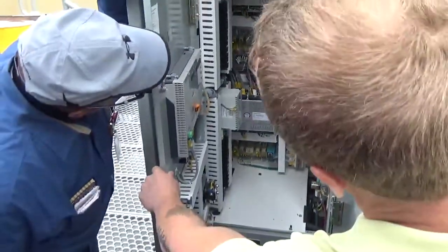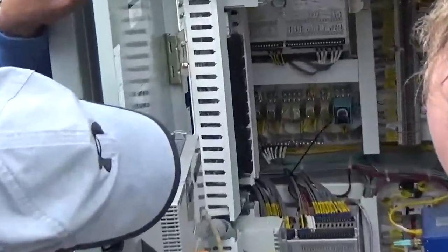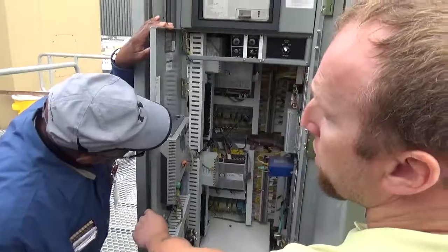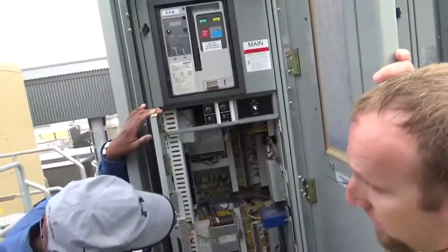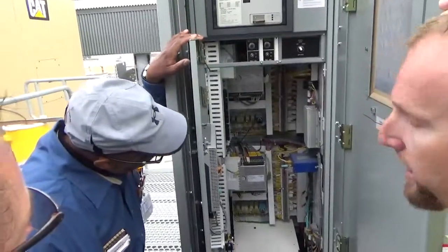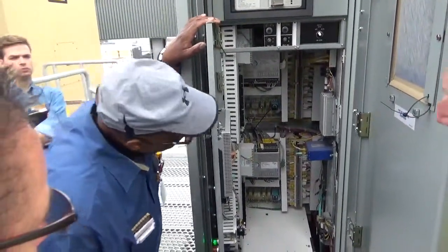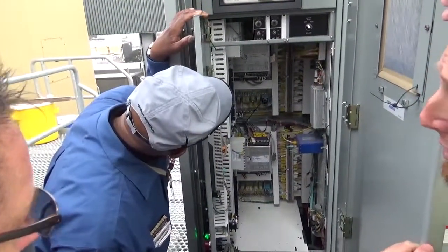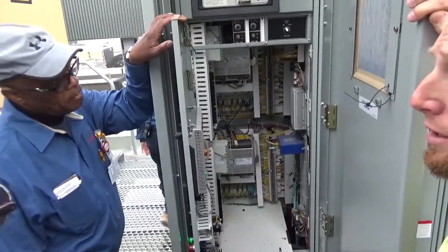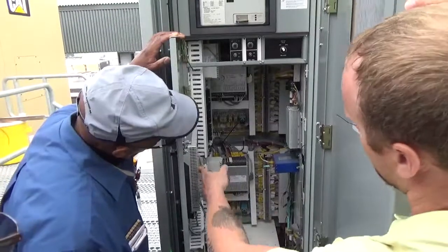All right. That blue box right there, that is your fiber to Ethernet converter. That is the signal that's sending it down to your remote panel, the remote one of these. And being that how far the distance is, that's why we have to convert it to fiber, send it all the way down, and then we take that fiber signal, reconvert it back to Ethernet, and plug it in.